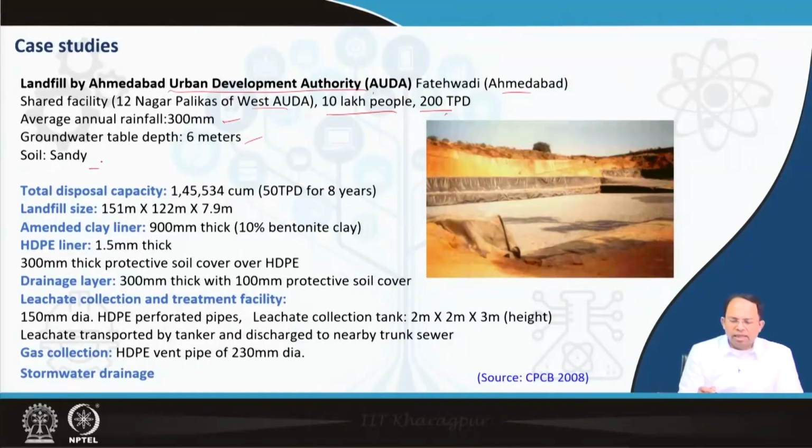Now, what design has been done? As you can see in this image of this particular landfill site, the total disposal capacity is determined considering 50 tons per day for an 8-year period, around 1,45,534 cubic meter. This is the total disposal capacity. Landfill size designed is 151 meter by 122 meter, and the height is 7.9 meters.